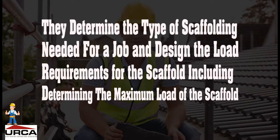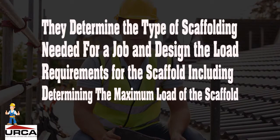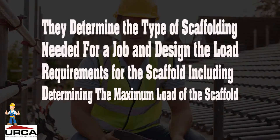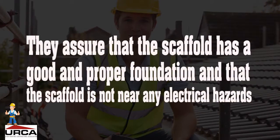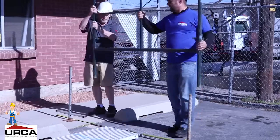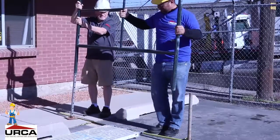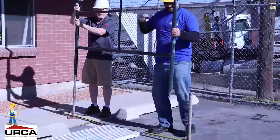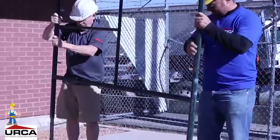They determine the type of scaffolding needed for a job and design the load requirements for the scaffold, including determining the maximum load of the scaffold. They assure that the scaffold has a good and proper foundation and that the scaffold is not near any electrical hazards. They ensure a scaffold has proper access when erecting or dismantling them, and that a scaffold is structurally sound when intermixing components from different manufacturers.